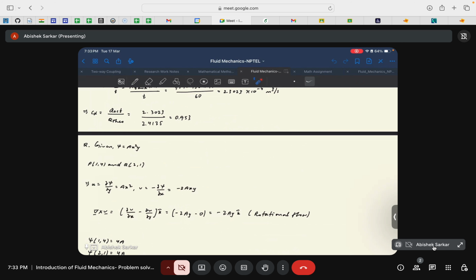So we cannot apply Bernoulli, but the flow field is steady, of course. That's fine. Flow field is incompressible because the stream function tells us that the flow field has to be incompressible. Then what's the next thing? Flow is inviscid, frictionless. They already told us. Correct. Let us just write it: your flow is frictionless, inviscid, steady, incompressible because of the definition of stream function.